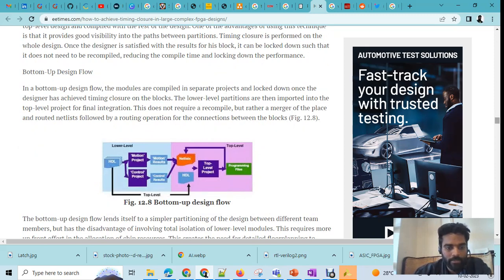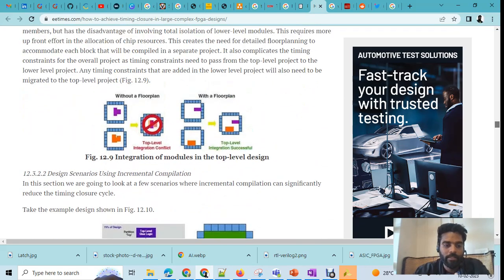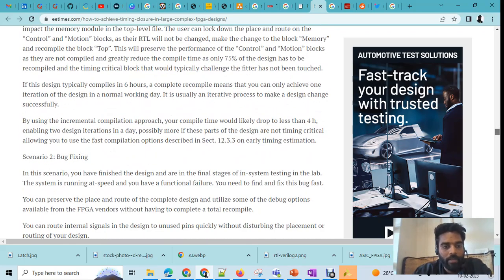Timing analysis will come after the synthesis part. In FPGA we have the front end and the back end part. The front end will do synthesis and so on. In the back end part, we pass the constraints as input, and we have the physical design part. The timing analysis will be done on the back end side basically. And for the constraints, we will have the clock constraints and the input and output delay constraints.